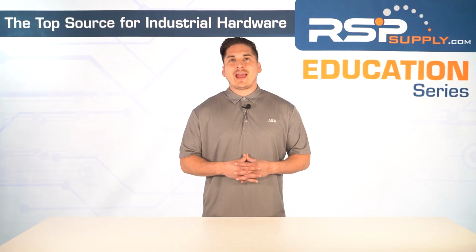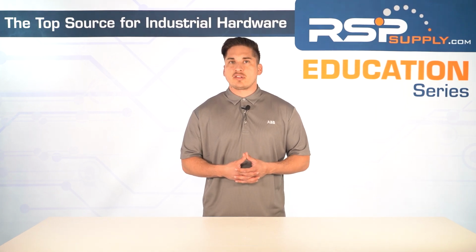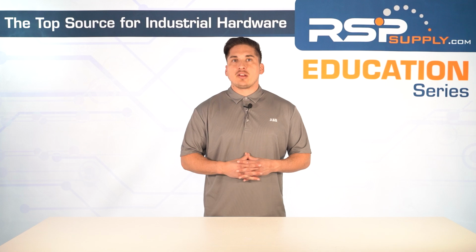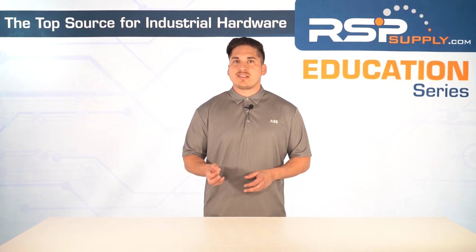So, 4 to 20 milliamp analog signals. This is the most common signal type used in process control. 4 milliamps is called a live zero. This means if the wire breaks, you'll notice right away. 20 milliamps represents the full signal range, like maximum flow or pressure. The big advantage is it's very resistant to electrical noise and it works well over long distances.